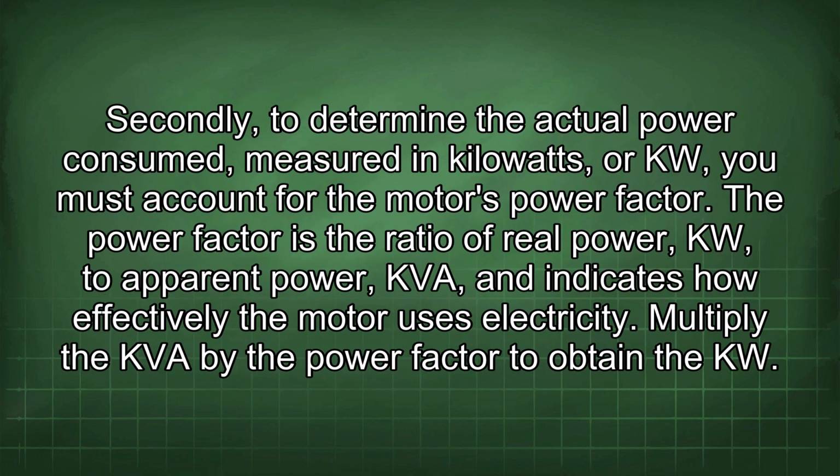Secondly, to determine the actual power consumed measured in kilowatts, or kW, you must account for the motor's power factor. The power factor is the ratio of real power, kW, to apparent power, kVA, and indicates how effectively the motor uses electricity. Multiply the kVA by the power factor to obtain the kW.